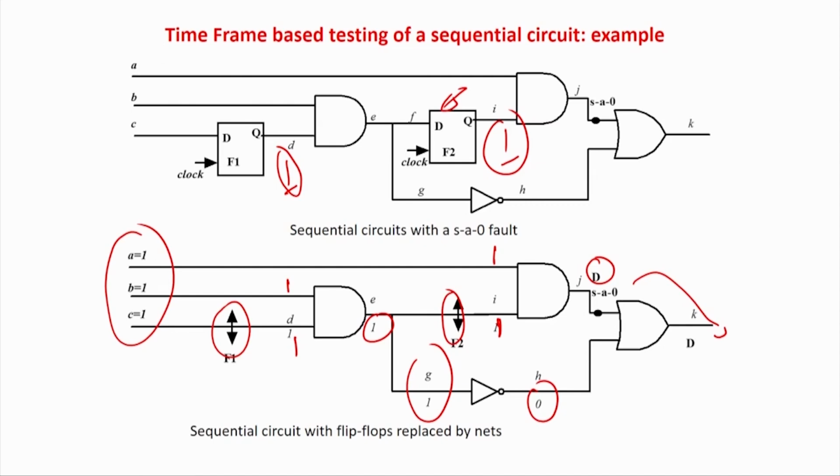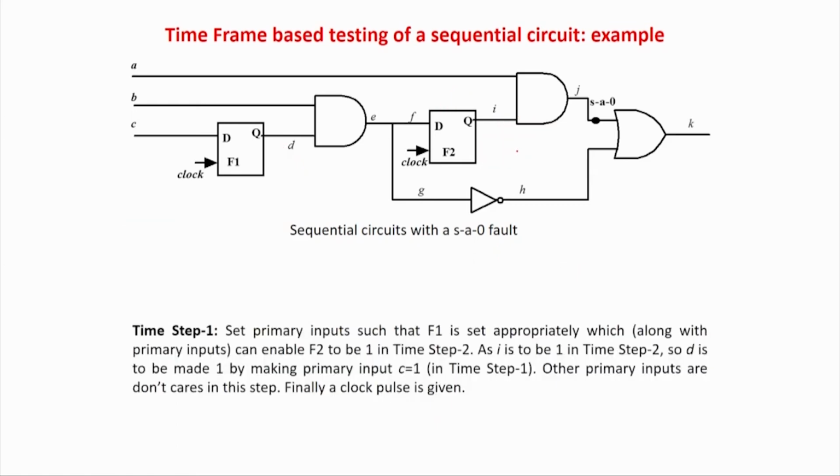But in case of scan chain, you do not do any computation after finding these values. You can directly apply them because they are scan. But if there is no scan, then you have to again do some kind of computation to find out how can I make 1 over here and how can I make 1 over here, and do it. We will show you. Now first thing is that you have to apply 1. How can you do it? Scan business, don't worry, ATPG is done.